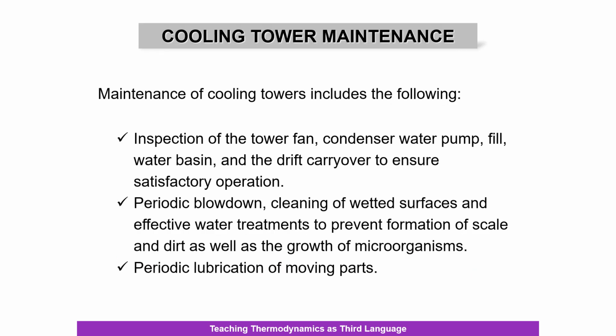Now, cooling tower maintenance is a very important issue. So there are a few aspects that you need to pay attention to. So one is you need to have inspection of the tower fan, condenser water pump, fill water basin, and the drift carryover to ensure satisfactory operation of your cooling tower. So that is why you need to have scheduled maintenance for cooling towers.